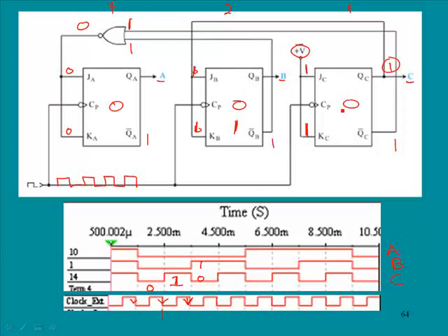Okay, now at this point we're at 1, 1, and 0. We're at 2. Notice this 0 is fed over here, and now there is a low here. Now that is significant because when we count to 3, which is going to be right here, when we go to 0, 1, 1, this has to remain the same. We were at 1, 0. Now we want to go to 1, 1. Well, this will stay a 1 because this 0 here is fed here.